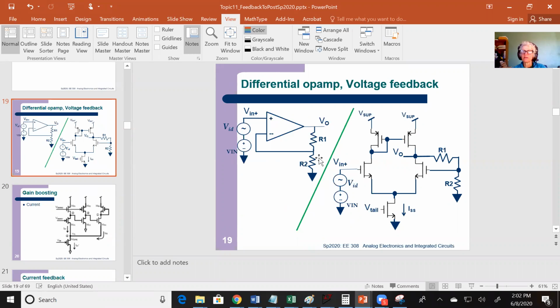So you want this to look like a big resistance. But this output right here should look like an infinite R in, sorry. This R in should be much bigger than the R out of this, so it's not stealing very much current. Just like a regular block, you want a high R in but a lower R out compared to what you're connecting to.